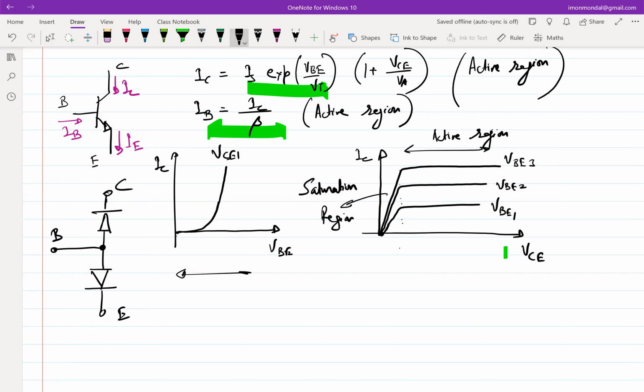So if you just look at the structure, the way the BJT is supposed to work is the control terminals are VBE, which means that in order to get amplification, you generally have to apply an input between VBE. And when you want a collector to swing, that is, you want a gain between collector and emitter, you are essentially observing the voltages between these two terminals. So in other words, this sets the current to some extent, and there is a certain current amplification that happens that is equivalent to the gm term in the case of a MOSFET.